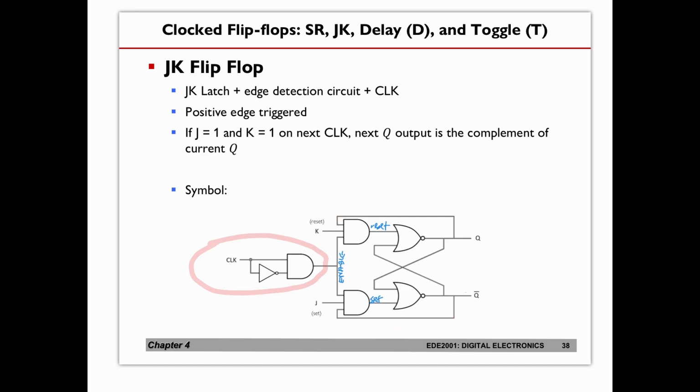So this whole item here is what we call a JK flip-flop, and this is one of the most versatile flip-flops. It lets us use this flip-flop to imitate many different flip-flops. We're going to talk about that in a short while. But what we are saying here is that we have a JK flip-flop which is positive edge triggered, from this circuit here.